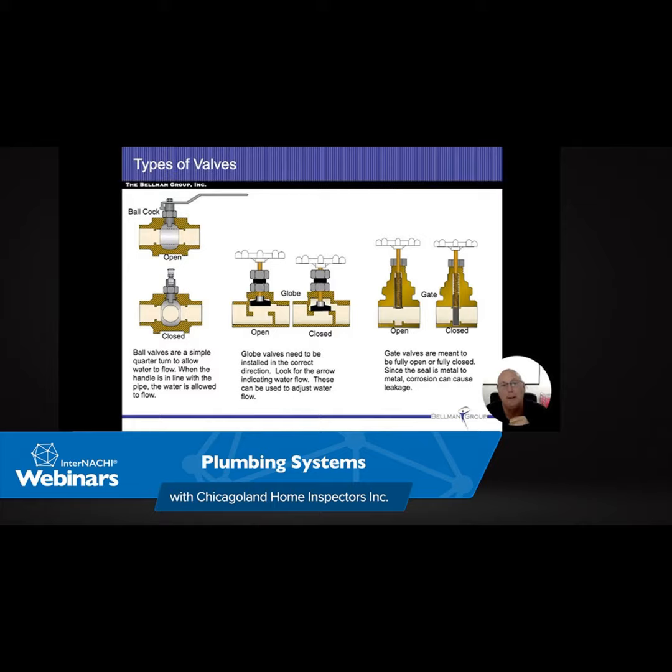Some people actually put big gate valves into them, and some people just had flapper valves that came up. Sometimes they went down, sometimes they went up, whatever. So the water would flow one way, and then if it was flowing backwards, the valve would close and stop it from coming up. All right. This is an actual one where you see it in the ground. Water's supposed to go in there. This one's hanging down from the top, so it prevents the water from going backwards and coming back into a house.